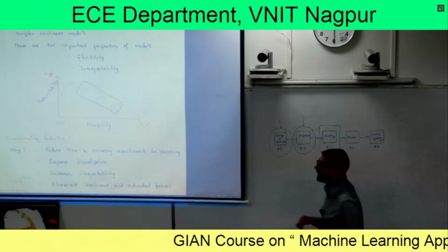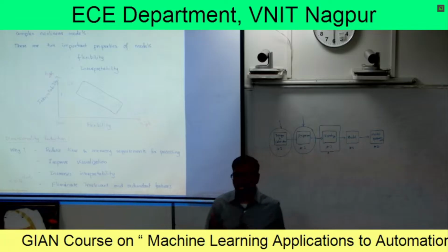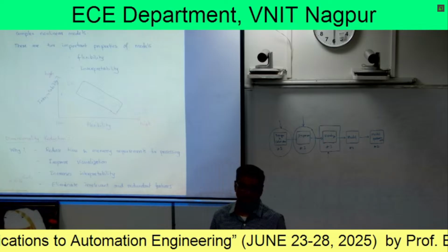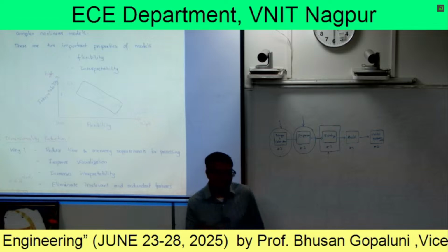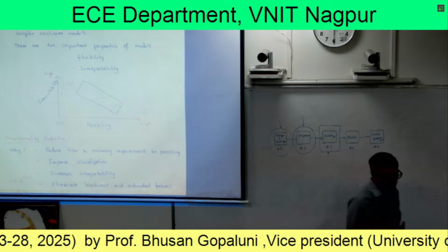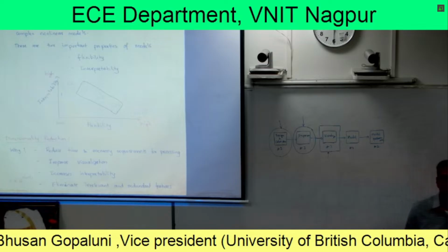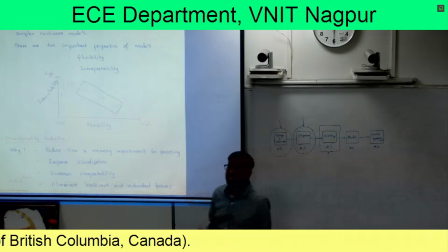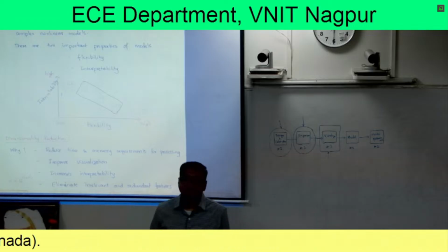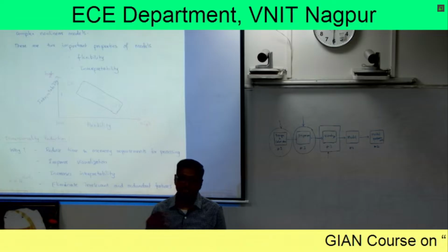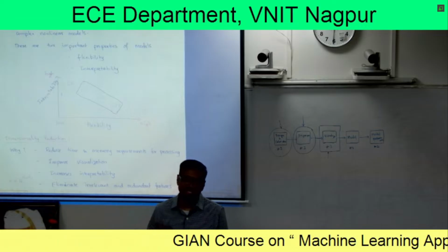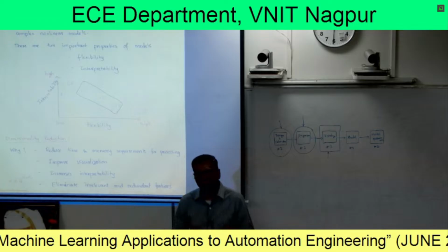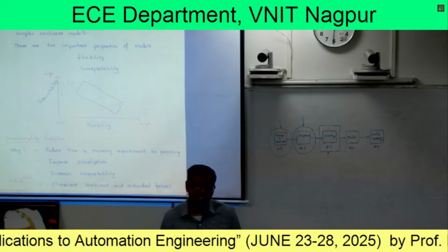You'll be okay by approximating the original complex system with a simple linear first order model, right? So your controller will do fine. On the other hand, if you want a model for simulations and some sort of optimization of your product or product quality, etc., then you might need a higher fidelity model that incorporates first principles ideas as well as some database information, right? So it depends on the purpose. Where do you want to use this model?